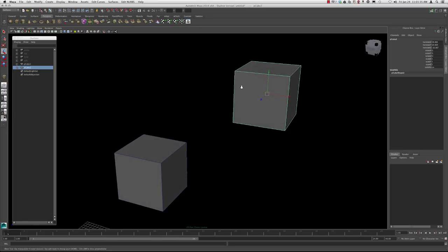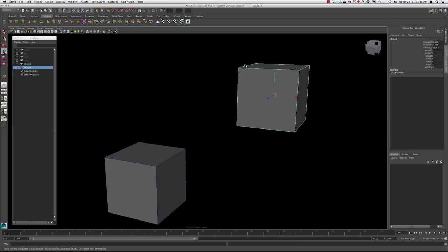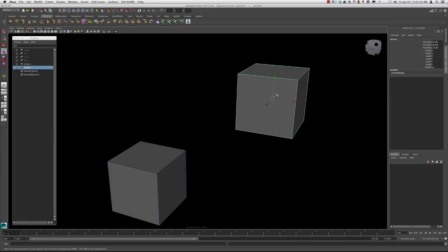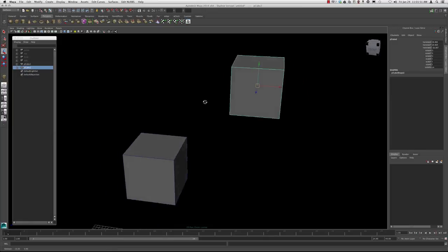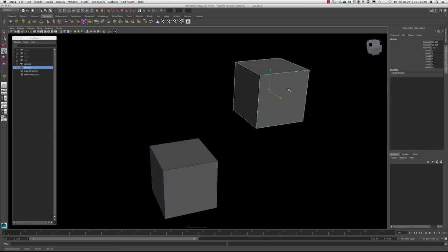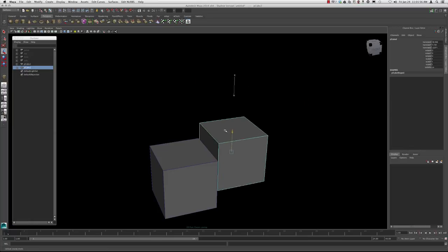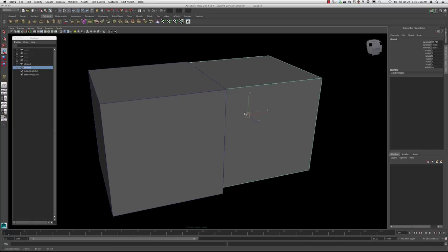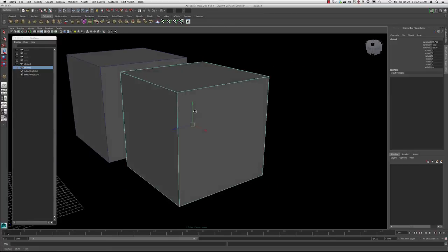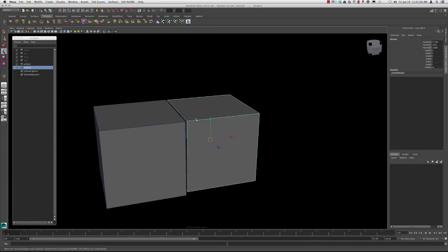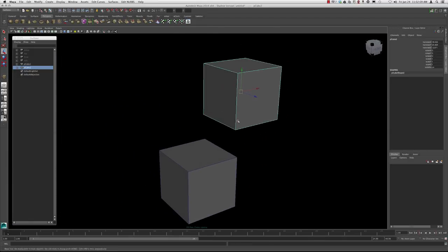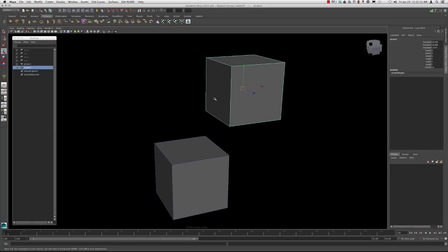So one issue though is, okay, well, we can move this from this position and the center to this vertex, but what if we wanted to move this polygon object from this position to the vertex so it lines up directly next to it? Well, you certainly wouldn't want to start grabbing and saying that looks close, because then when you move over here, you realize it's not remotely close. So one way to do this is by changing the pivot position.